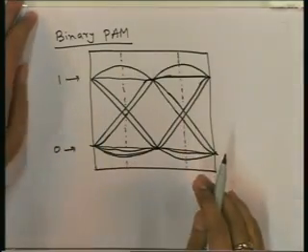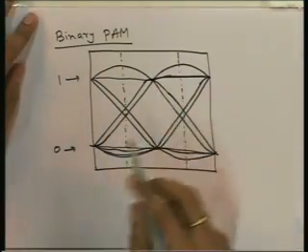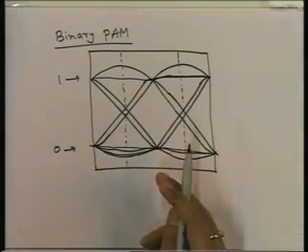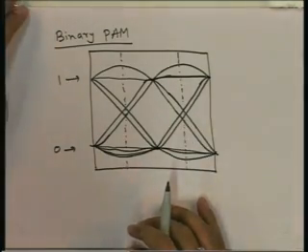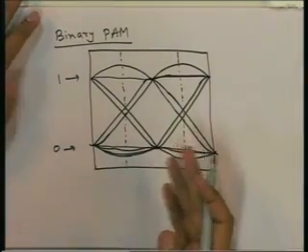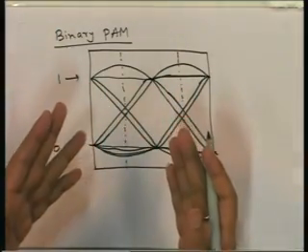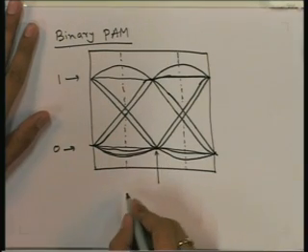And why is it called an eye diagram? Because this looks like an eye. And what is the use of this diagram? Now let us see how we do the detection at the receiver. We know that this is the output of the matched filter, that is the receive filter, for which the matched filter is optimum, and we will then sample. So, these are the optimum sampling times.